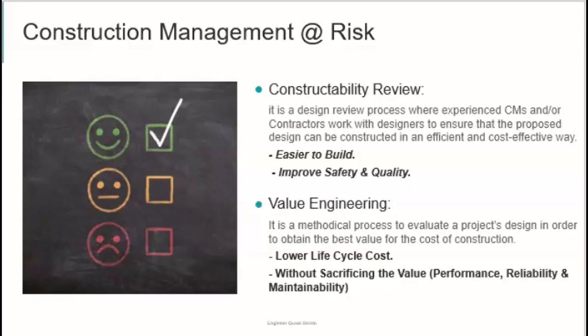It's for their own benefit, the whole team. They check if it's easy to build, and the general contractor plus the subcontractors, in some cases the specialty contractors, with the design team, they come up with a way and review the plans to also improve the safety and quality. Even if you apply for projects, you can see the CM has to have experience in value engineering or constructability review. The value engineering and constructability review are somehow similar, but the value engineering process is more detailed.